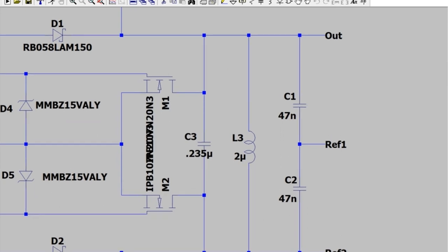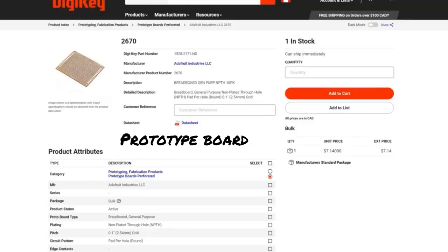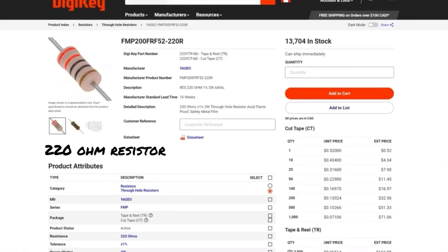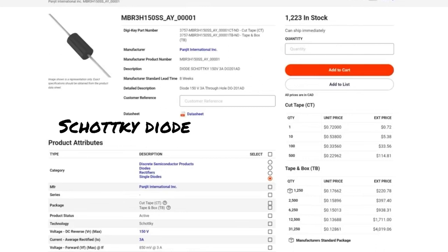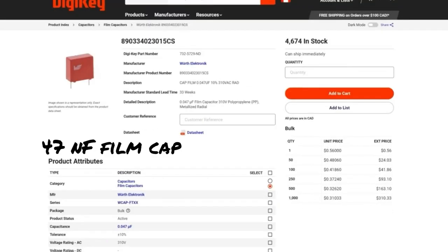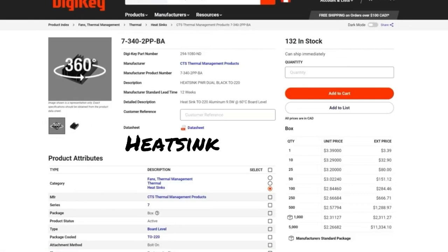My new and finalized inquiry question is, how can DC voltage be used to generate a changing magnetic field in a solenoid? The way it works is, it contains an inverter circuit which converts DC voltage to AC using a self-resonant oscillation system of 2 MOSFETs, 2 Zener diodes, 2 Schottky diodes, and capacitors. This allows the solenoid work coil to have induced current and therefore induce current in conductive materials.